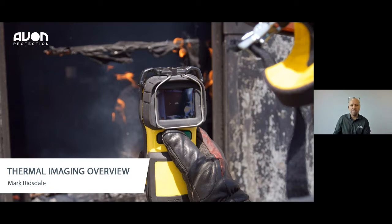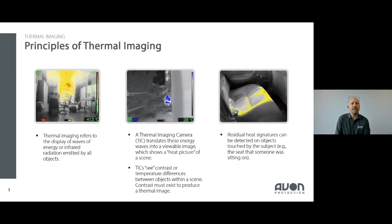Okay, so we'll move on to the first slide. So basically, when we look at thermal imaging, we refer to it as the emission of infrared waves or infrared radiation. And what thermal imagers do is they translate that infrared energy into a viewable image. The way TICs, or thermal imaging cameras, as we call them, work is they see the contrast differences between different temperature areas, and therefore contrast must exist in an image in order to produce that image.